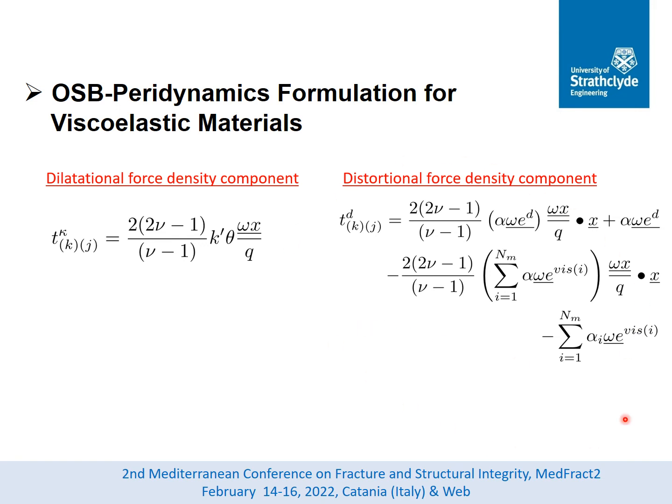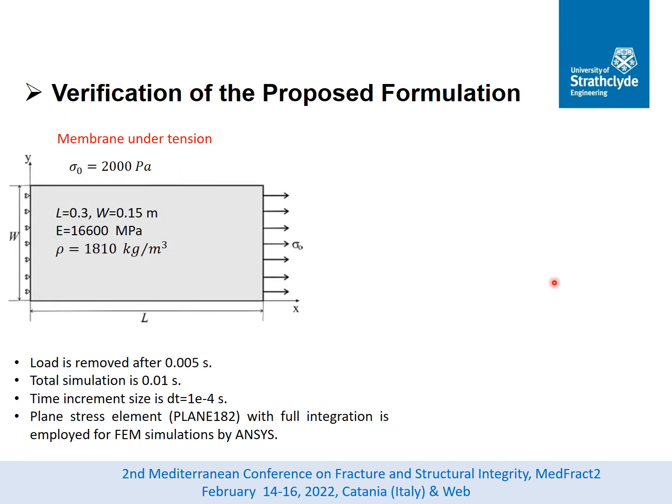As you can see here, there are some extension terms with the viscous deformation. E vis represents the viscous deformation for each Maxwell element in the Prony series. So I have briefly described the ordinary state-based peridynamic formulation. Now we can proceed to the verification of our formula.